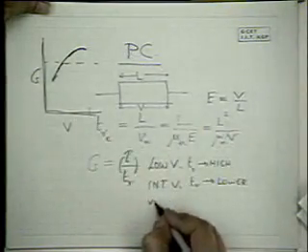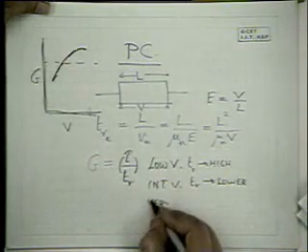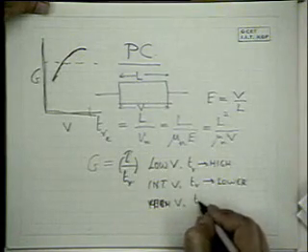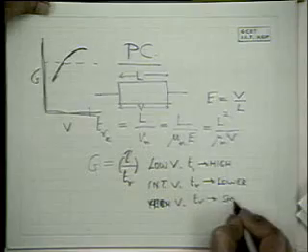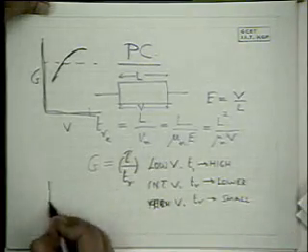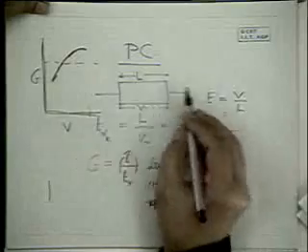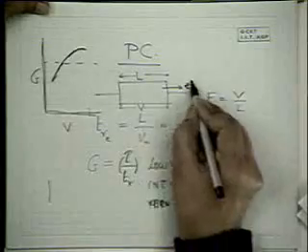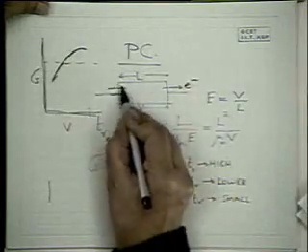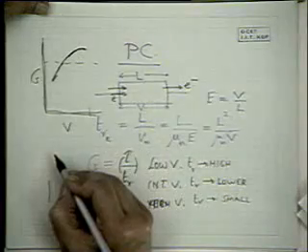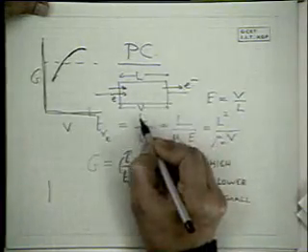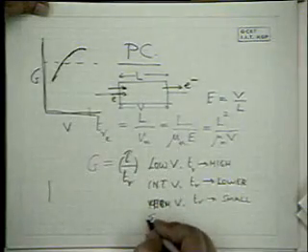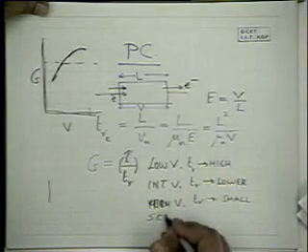Then at very high values of V, TR is no doubt small, but when the electrons are swept away very fast, we have increased injection of electrons, and as a result we have a condition called space charge limited currents.